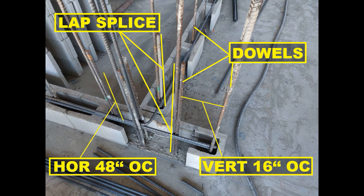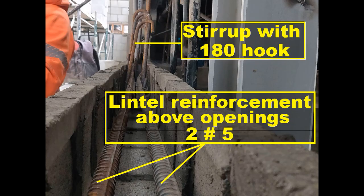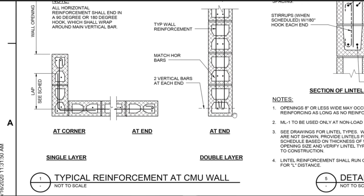CMU foundation dowels. Dowels lap splice. Bond beam reinforcement at the top of the wall with 2 number 5 rebar. Additional bar at openings. Let's move to detail 1. Typical reinforcement at CMU wall.